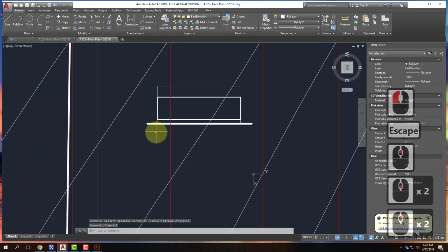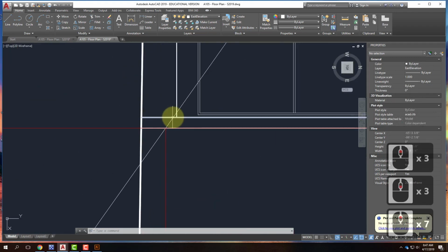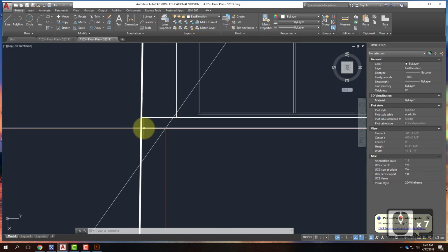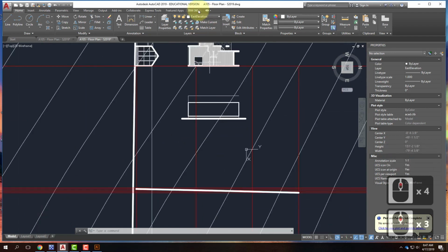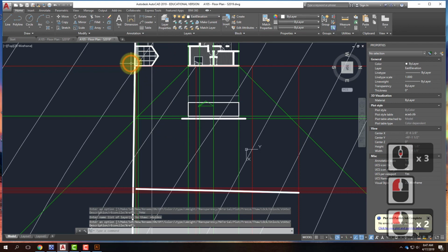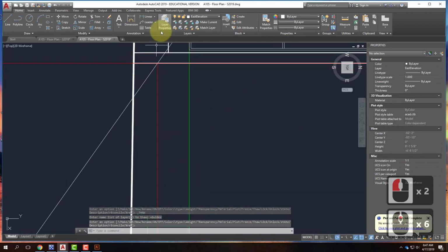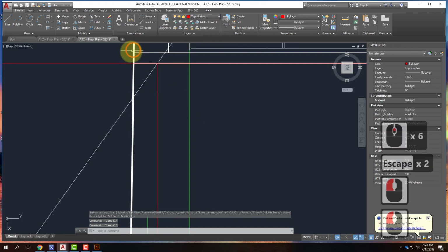This, however, gets a little bit trickier in that I have to match up on this corner right there. The terrain hits the building at this point, which is further down than it is here. So I need to make that correction. So I'm going to turn back on my regular guides, and I'm going to create a ray and jump into my Topo Guides here.